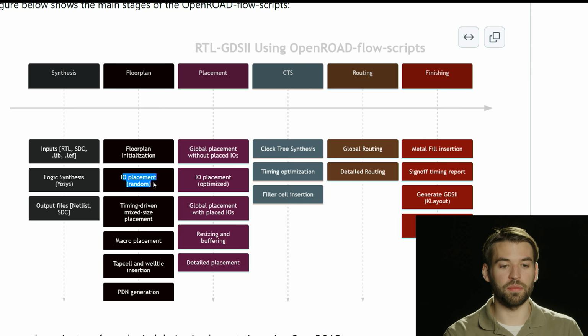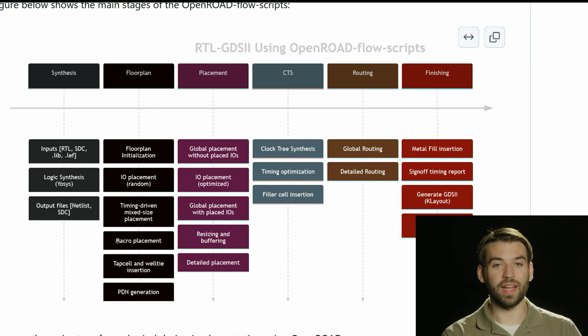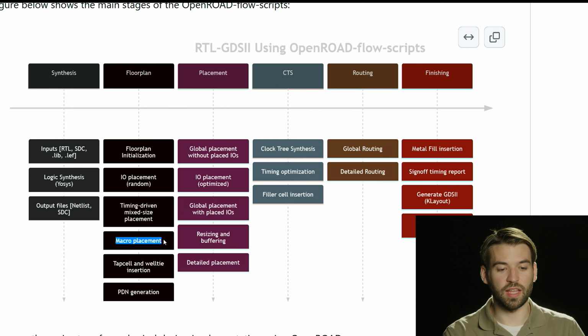Those should come from your RTL, your Verilog code, etc. And then you'll decide where those get placed. And then you'll first make decisions about any large macros in your design, where those will get placed. So macros are things that typically do not fit in standard cell rows, the DB rows that we have, and so they'll get placed first because we need to lock in their positions.